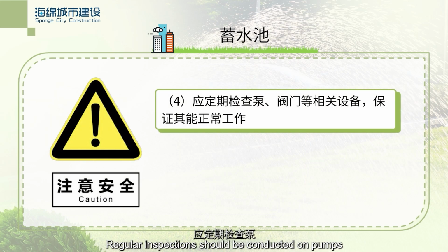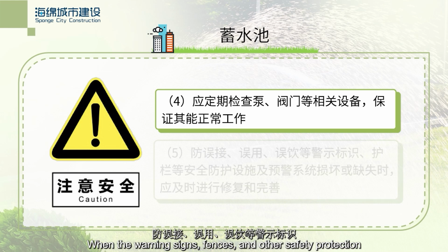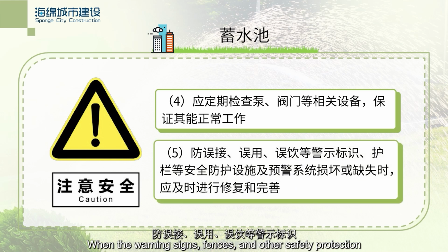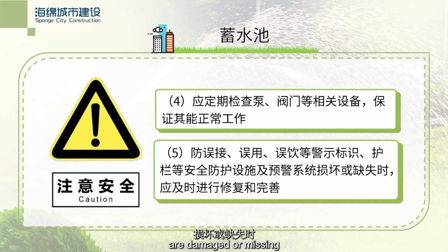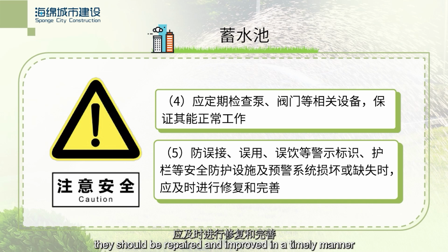Regular inspections should be conducted on pumps, valves, and other related equipment to ensure proper functioning. When the warning signs, fences, and other safety protection facilities, as well as the early warning system, are damaged or missing, they should be repaired and improved in a timely manner.